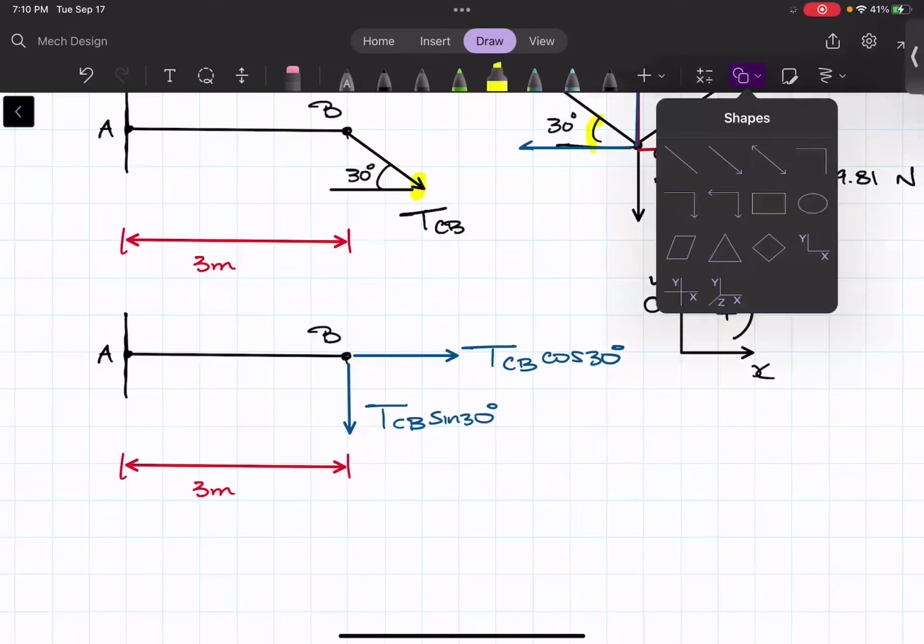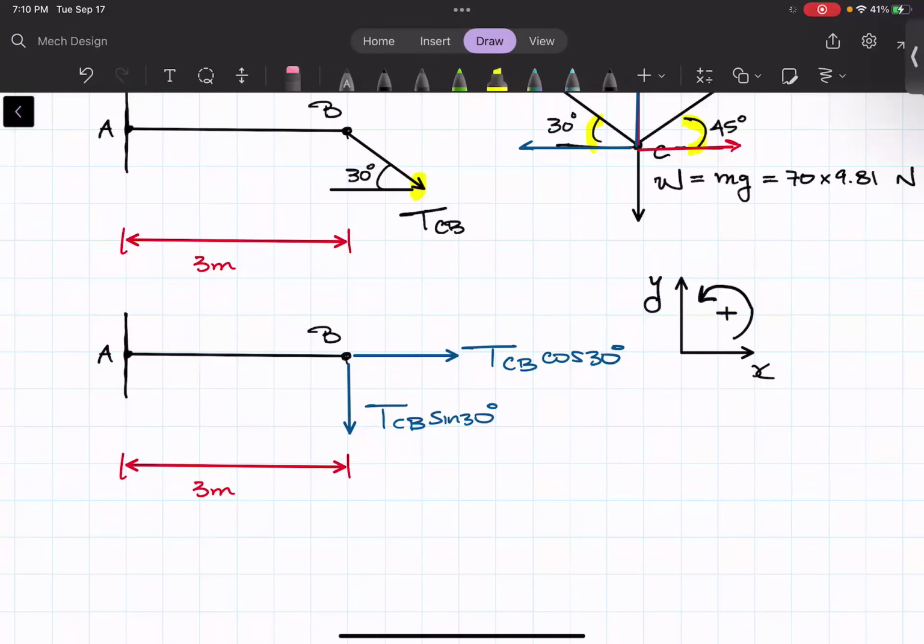If we look at the X component, the line of action of the X component of the force, I'm using it highlighted yellow, that's the line of action, okay? If the line of action intersects the point of interest, in this case A, then that means there is no moment component, okay? There is no component. That X component force is not creating a rotation, right? It's essentially pulling the beam rather than rotating the beam, okay? That's how a student should visualize moments, okay?